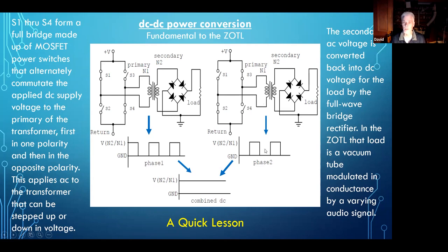So that gives you the opposite or the opposing phase, which fills in the square pulses on this side, out of phase from that side. You combine these two with the bridge rectifier and you get just DC, straight DC. Now this is all ideal. I'm not showing any parasitic effects or anything. This is just ideal, but it's not far off from the truth.